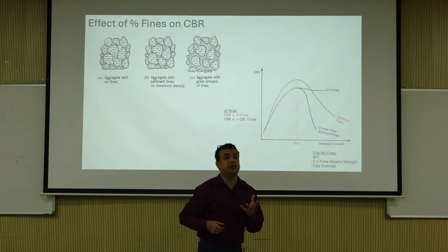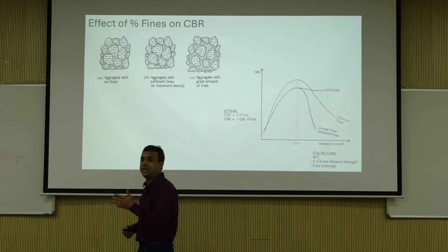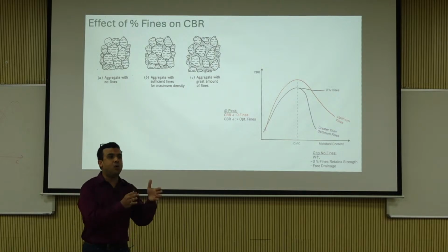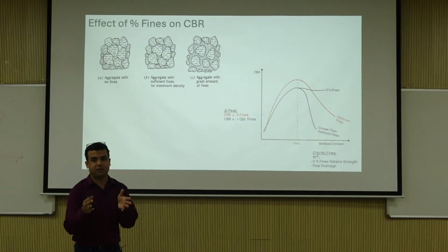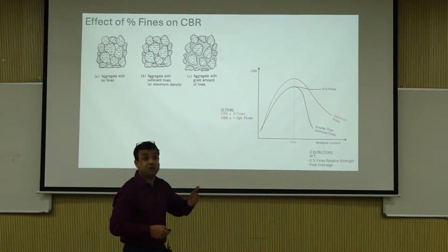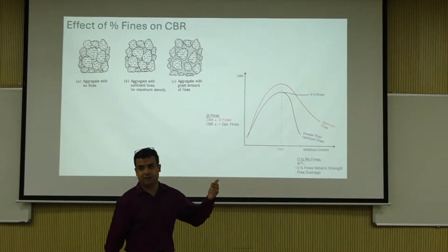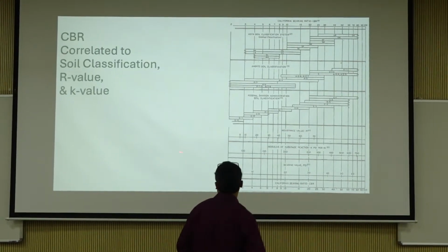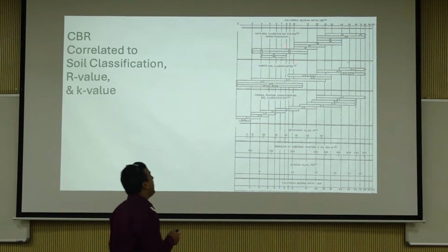So that's what I was talking about in the railroad ballast example, the fouled versus unfouled, right? If it's fouled ballast and it is dry, it can actually be really good sometimes. The problem is when it rains. It collapses, right?